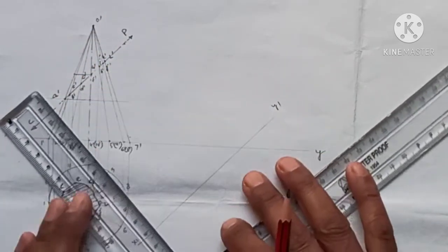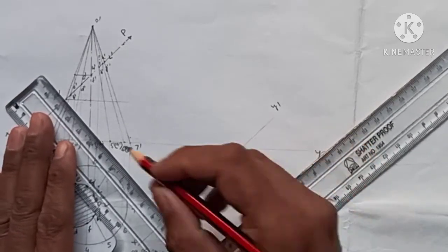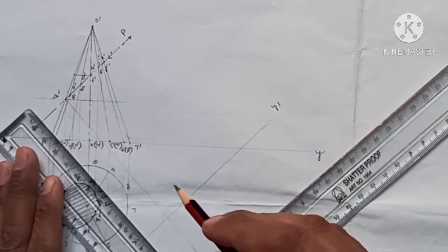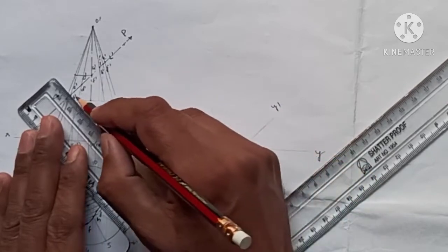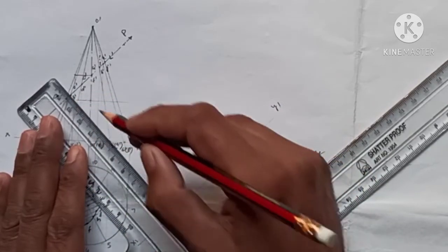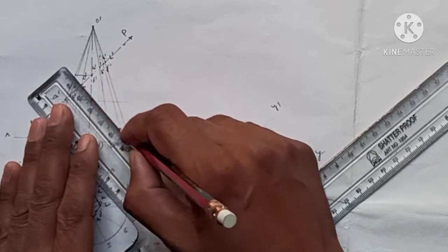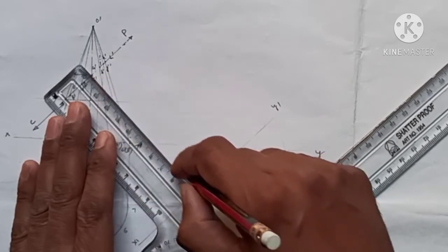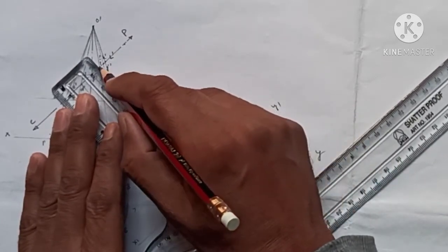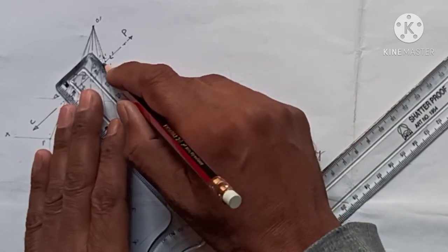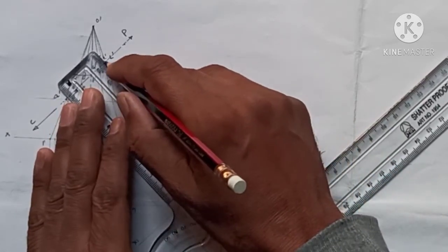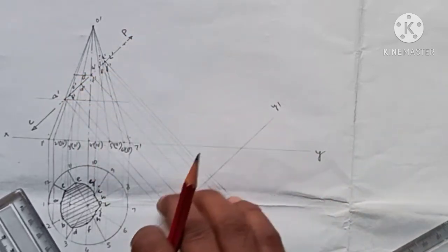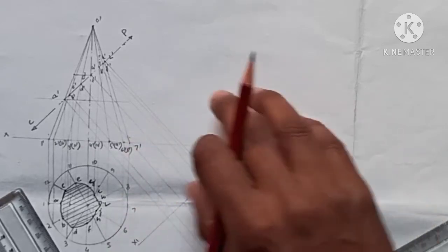Now what next I need to do, I need to draw the lines perpendicular to this from all these points. So I will draw all these points on this line. Fine, so this was this one point, and same I can go with the other points. I need to draw all these points perpendicular to this x1 y1 line. Fine, my dear students, I hope you are getting me in a nice way, because I have to get the true shape of the truncation. Okay, this is what I brought, all these lines perpendicular to this x1 y1 line.